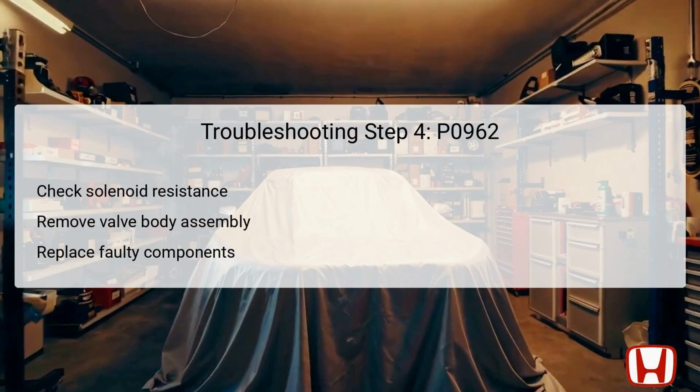Measuring resistance between the appropriate terminals allows you to determine if the solenoid valve operates within the specified range, ideally between 4.6 to 6.3 ohms. If the resistance falls within this range, the solenoid valve is functioning correctly, and the next step would involve inspecting or replacing the associated solenoid wire harness.